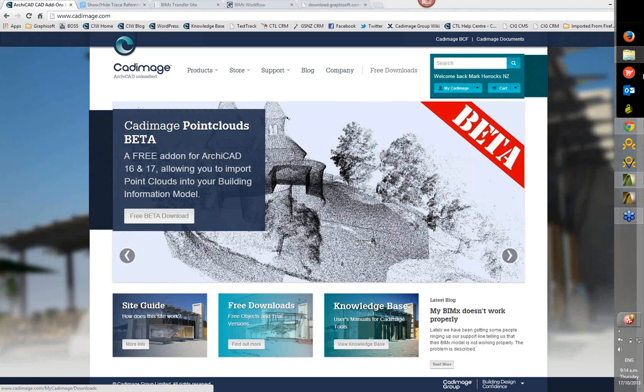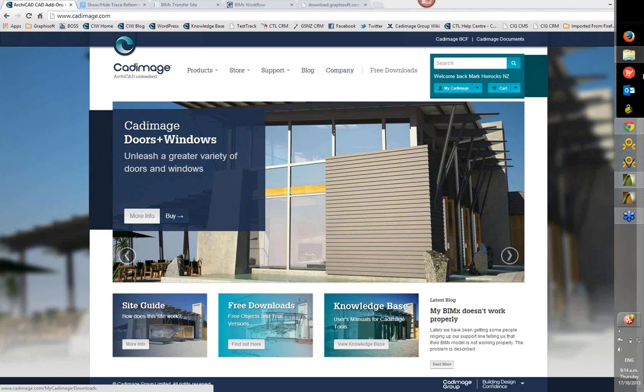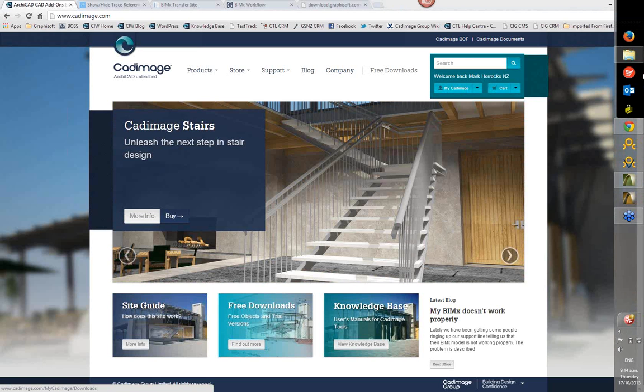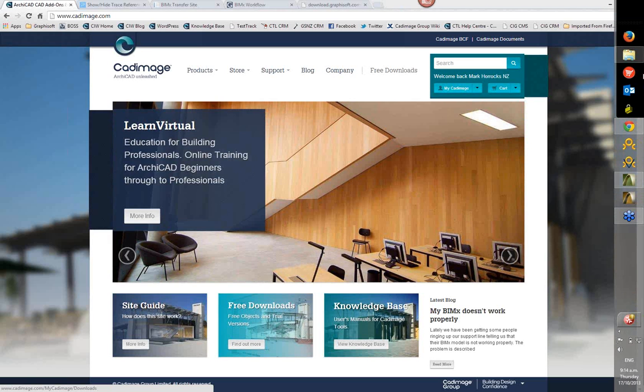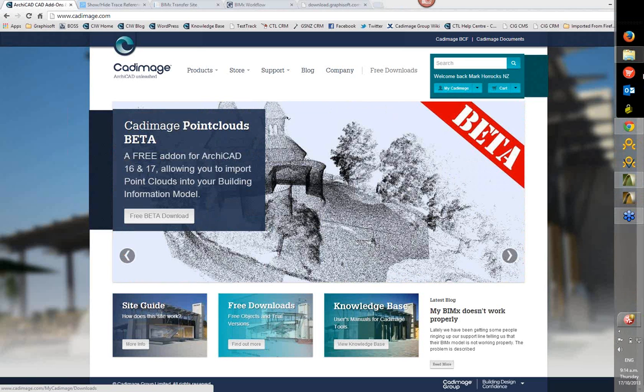All you need to do is, if you haven't already, replace zones, because energy evaluation works in conjunction with the zone tool, which it didn't in version 15. If you're migrating energy evaluation from 16 to 17, it just migrates seamlessly, and then you get all the new features of energy evaluation in version 17.